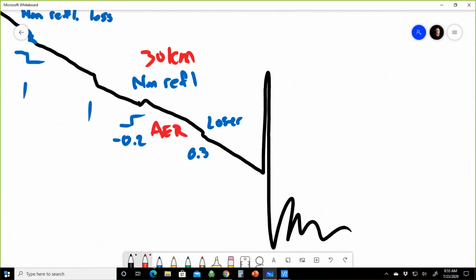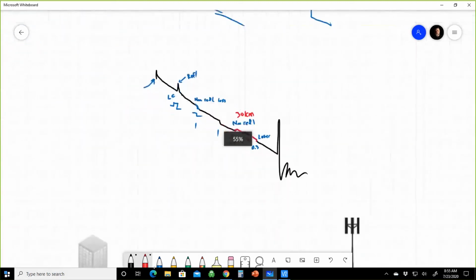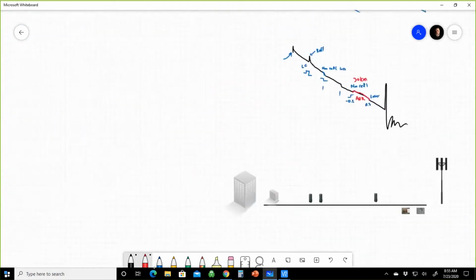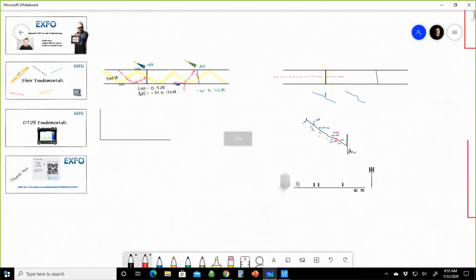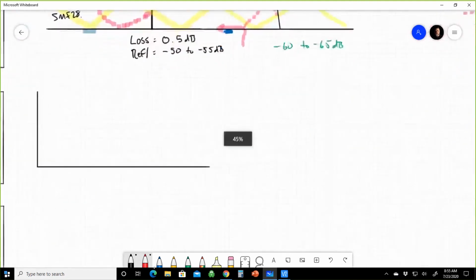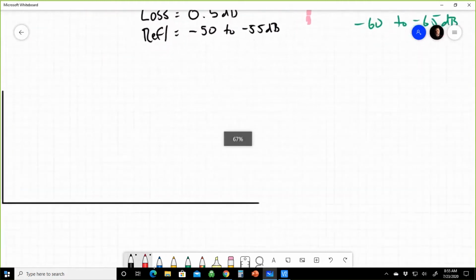So that tells us that there's a change of fiber type, at least from OSP to aerial cable. And so there might be a mode field diameter mismatch. They can be the exact same type of fiber, SMF 28, G.652. They just have different vintages. And so I used to like doing troubleshooting like this, like, this section, that's that one aerial section. There's that change in fiber types. And so that's some of the advanced OTDR stuff that we try to tie in, right? We try to tie that information in. So that's what an OTDR does. It sends out a pulse of light and it interprets that backscatter.